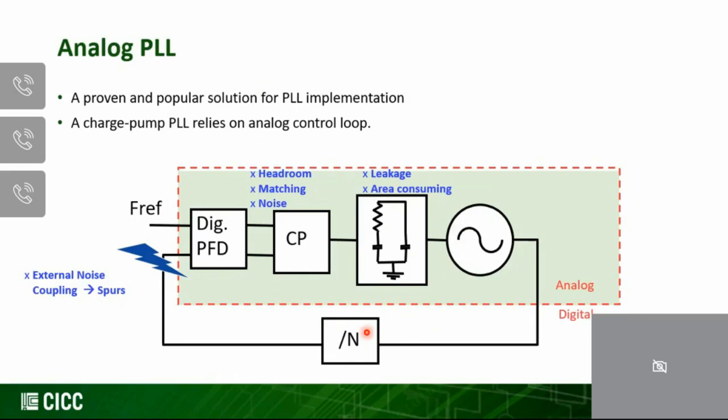On top of that, we also face external noise coming from other parts of the circuit. For instance, today, when we implement SoC platforms, it's very easy to pick up some noise from other circuit blocks, for example, from digital blocks or from other clock generation blocks. So we constantly face those different noise couplings to the designed phase lock loop.